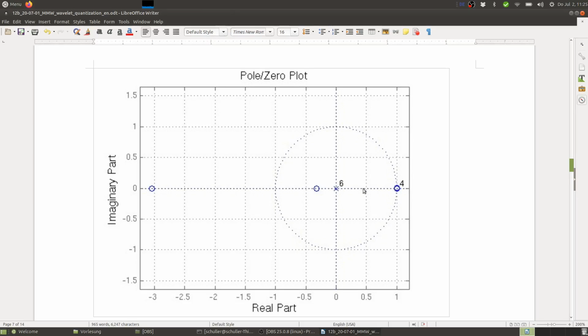So remember, the DFT is simply a finite length version of the DTFT. So it's basically what we use to obtain our frequency response. Then frequency 0 means e to the j omega equals 0, means real 1. So this is 1. This is frequency 0 then. And e to the j omega equals pi means Nyquist.